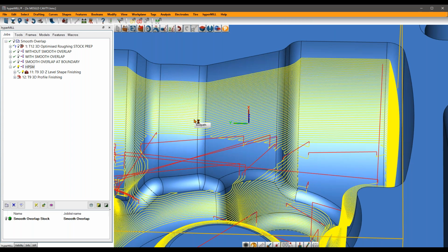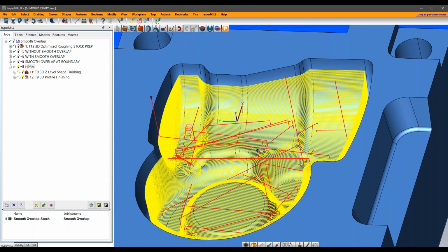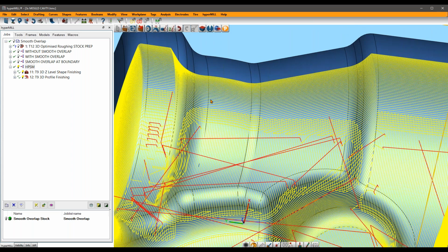Now, in working with your machine, okay, high precision surface mode is creating a much better point distribution on your surfaces, and your machine with its smoothing code is splining through these points, ultimately creating a better surface finish.